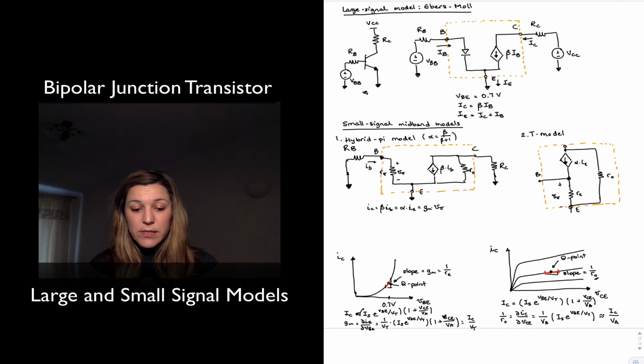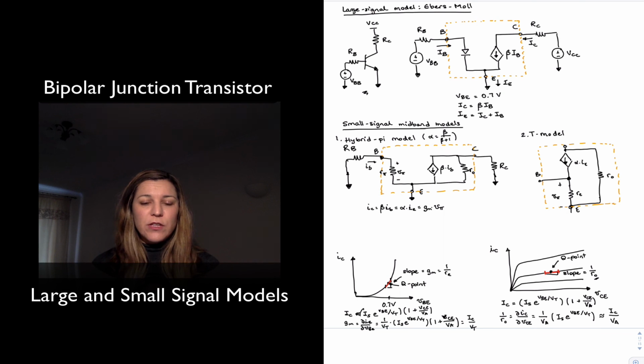One more thing to notice, and I guess it's written here: when we are talking about transistors, as a first order approximation, we said we're going to consider at least the BJT as a current gain device, meaning the collector current or output current is equal to beta times the input current, which is the base current. But a more general way of thinking about transistors, which applies both to BJT and MOSFET, and perhaps a more accurate way of looking at them, is as transconductance devices, where the input signal is actually a voltage and the output is a current.